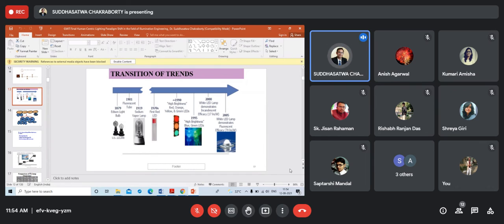We hardly used to think there could be a 10 watt LED. So if we were about to create a 30 watt luminaire, it was a huge deal to have the thermal management and the lumen output, but there was no option. But now a single LED luminaire can provide 1.8 kilowatt. That's how the development has come. That's how the lumen per watt now, according to the companies, is sometimes 100 lumen per watt.